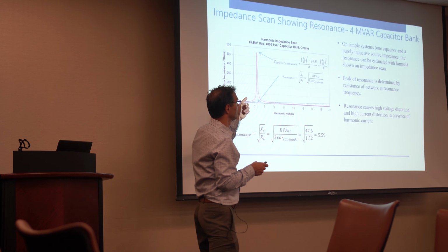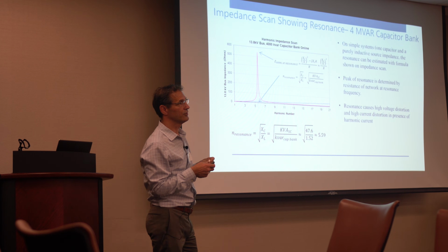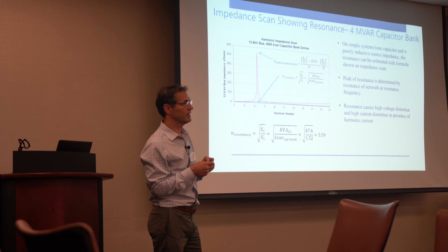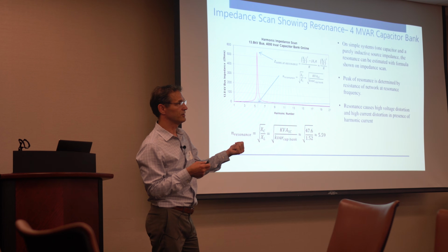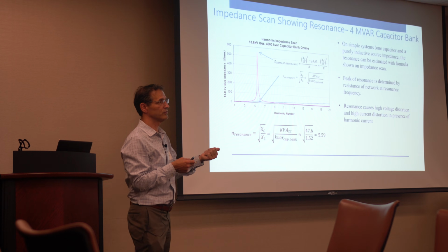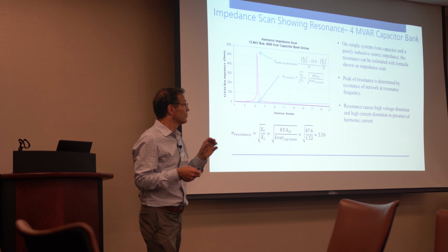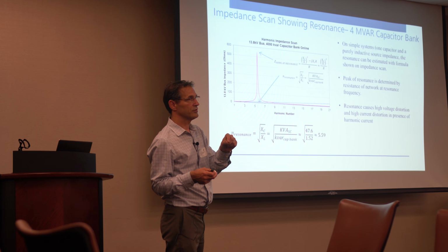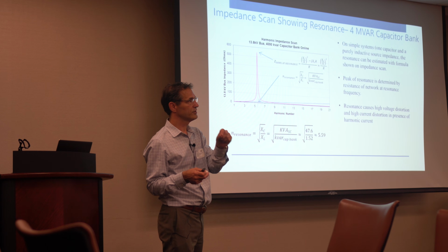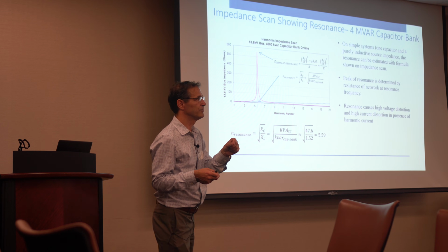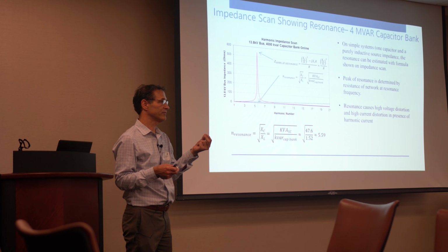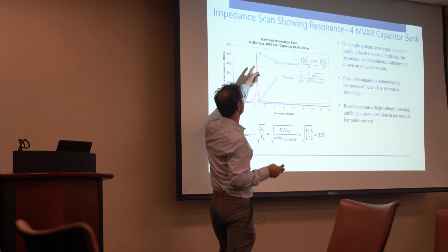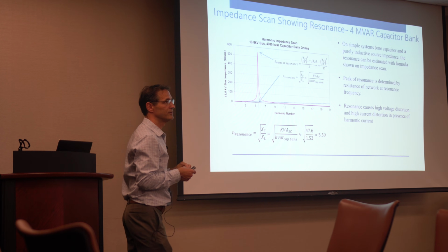The other thing about R in the network is it's an unknown quantity. It's not easy to quantify. The nameplate rating of the transformer does not contain the resistance of the transformer, so it's a value that's already difficult to quantify. And resistance is impacted by frequency, skin effect, and proximity effects. So you may be able to say you know the resistance, but only to a degree do you know the resistance of the network. So the magnitude of this peak becomes a question.